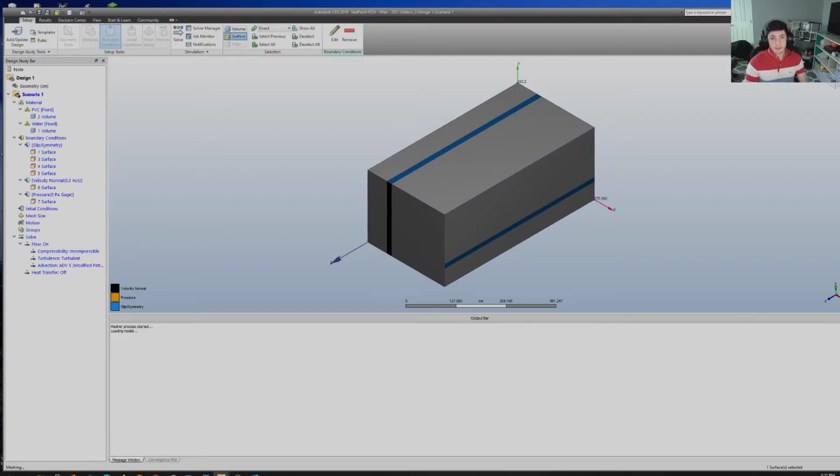So what is happening now is, just to recap, the CAD was taken from Inventor into CFD. When you create that CAD in Inventor, it makes a bunch of really big triangles to create the volume and surface of it. These triangles are brought into CFD and divided into smaller triangles to create a good resolution mesh.